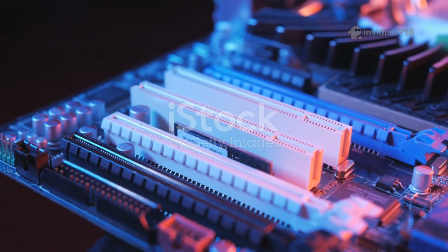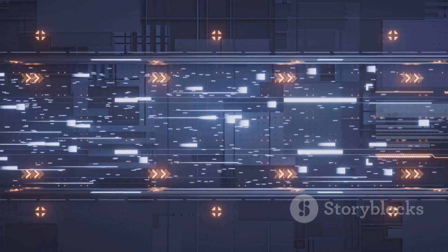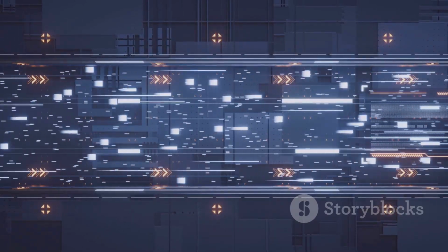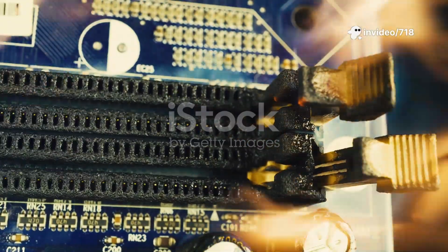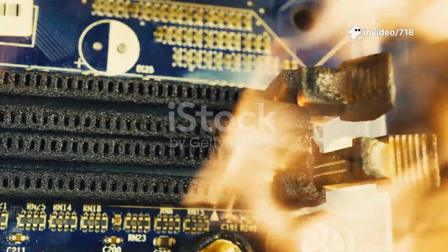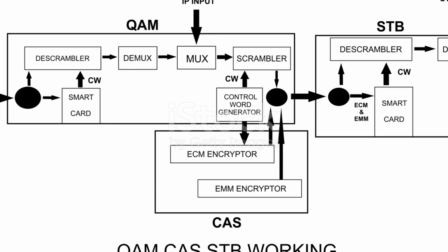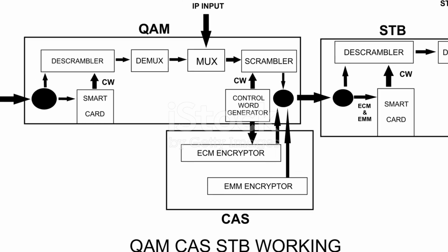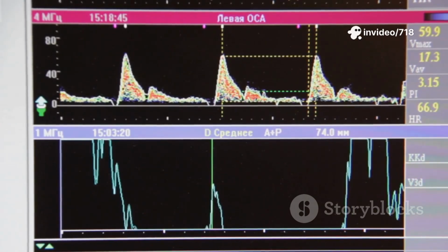Timings are a set of rules that define how long the memory controller must wait between different commands. You can't just issue commands as fast as you want. For example, there's a specific delay required between activating a row using the RAS, or row address strobe, command and then asking for a column from that row using the CAS, or column address strobe, command. This is called the RAS to CAS delay, or tRCD.